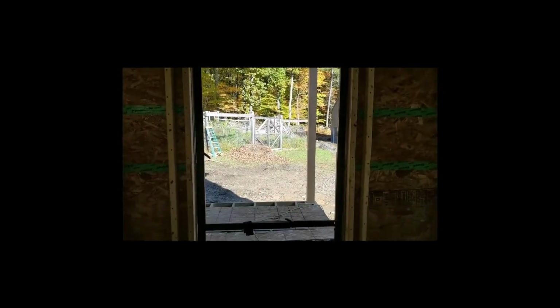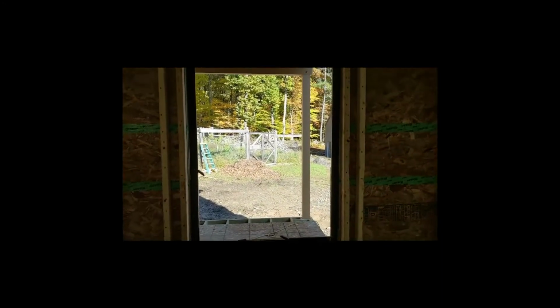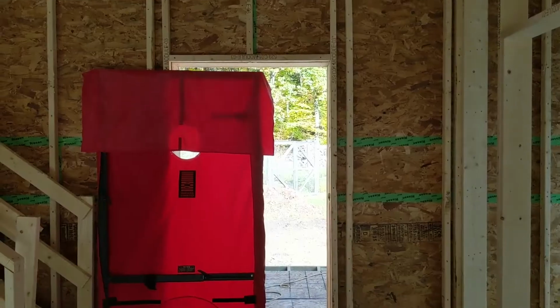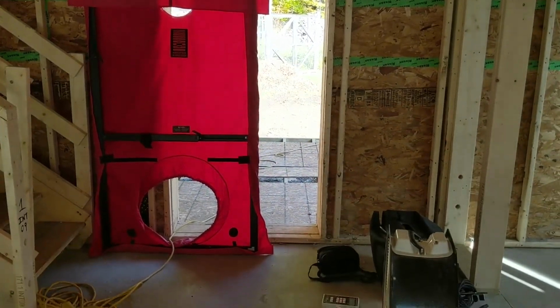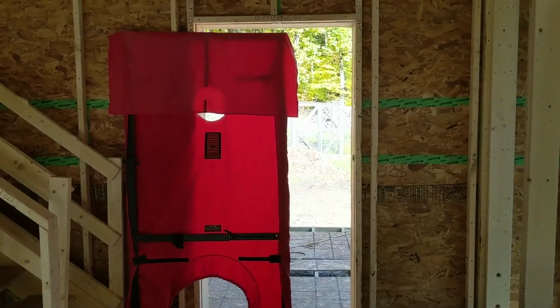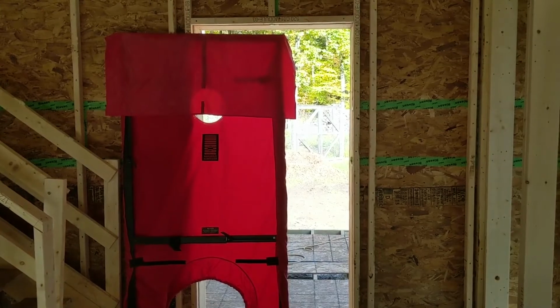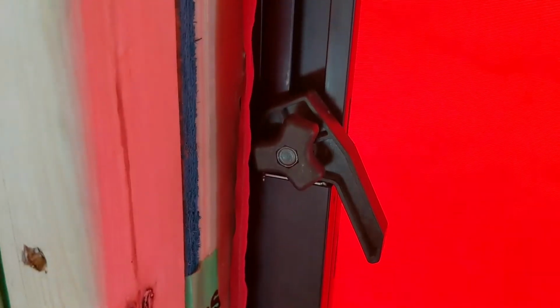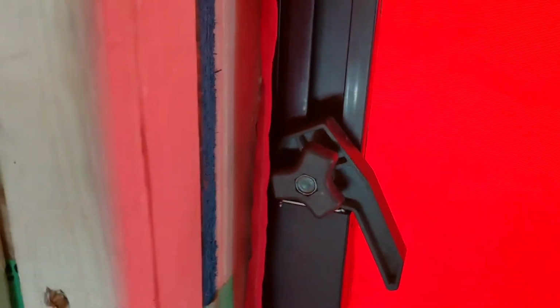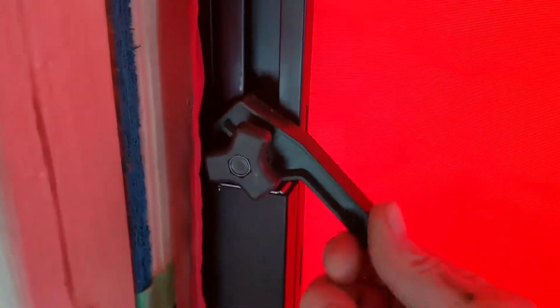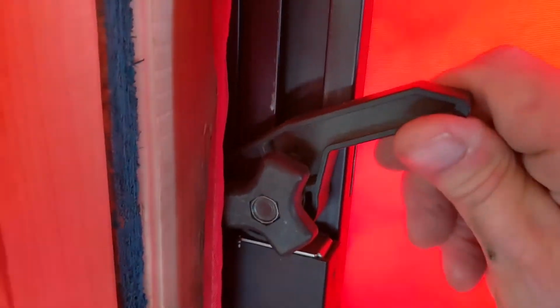So now I have the frame loosely set up in the rough opening. I want to leave a little space around it so that I can fit the shroud around the frame. And so I've got the shroud wrapped around the frame, fastened loosely in place with Velcro, and then I'm going to put it into the rough opening and tighten it up. So the way the frame tightening works is you've got these knobs that you extend the frame and then you tighten this knob, and then once the knob is tightened, to get that extra bit of tightness and seal the frame against the gasket, you use these cams.